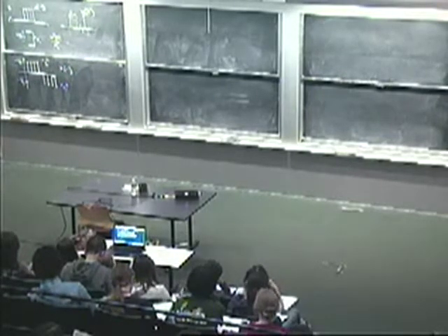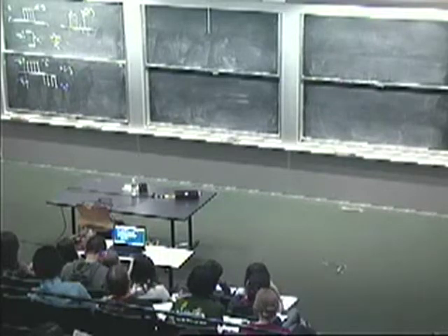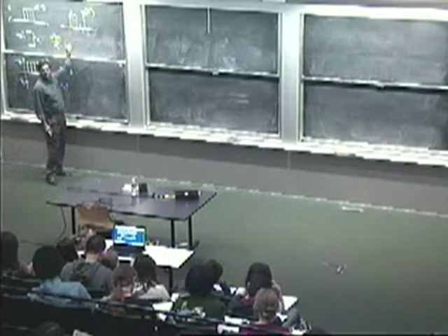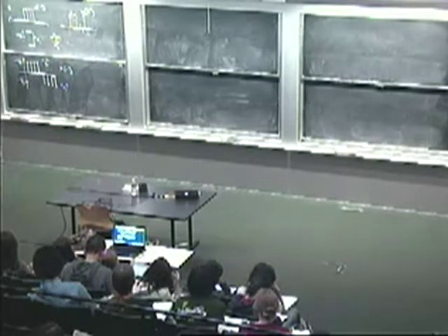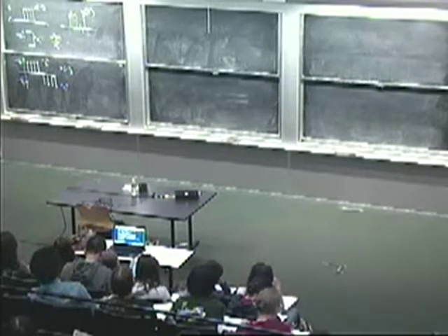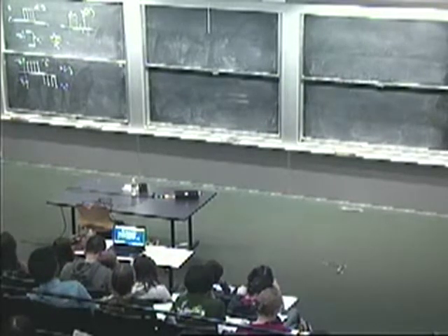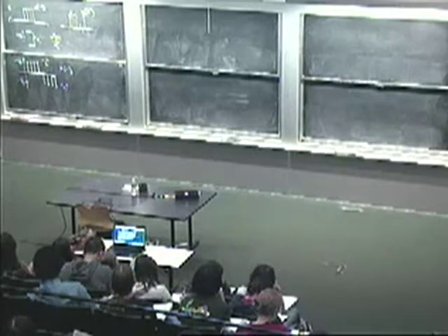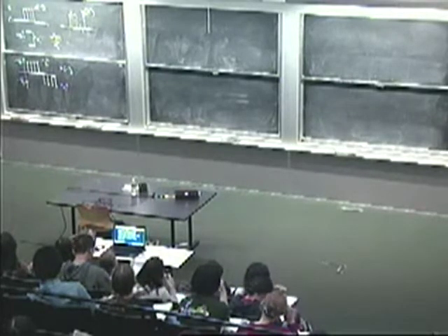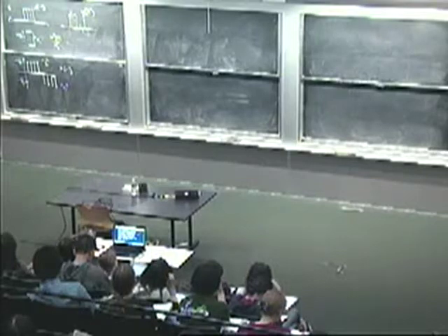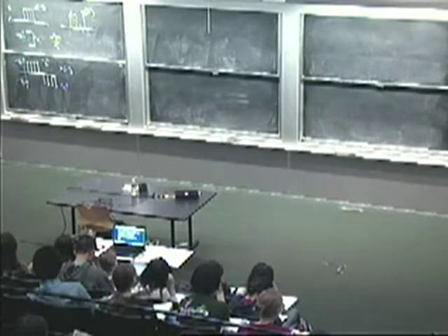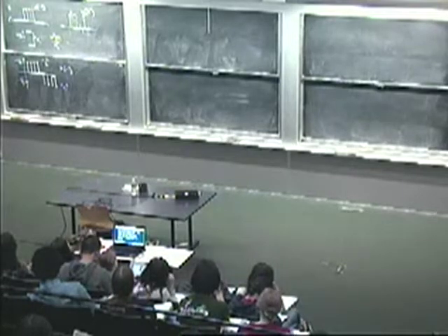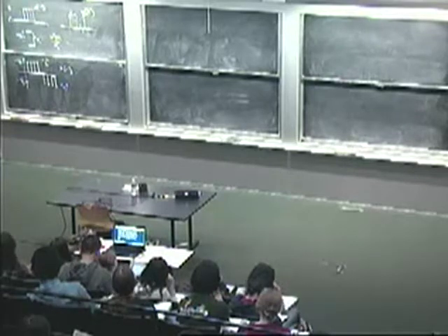And at the receiving end, I pick one particular sample to look at. Let's say it's sample n sub j, so maybe I'm looking in the jth bit slot, and I pick one particular sample time, let me call that n sub j. I have to decide: am I looking at plus Vp with noise, or am I looking at minus Vp with noise? That's the decision. I know the Vps. Assume that we've taken care of the scaling and so on across the channel. And I know the characteristics of the noise. I know that the noise samples are Gaussian, zero mean, and some variance.